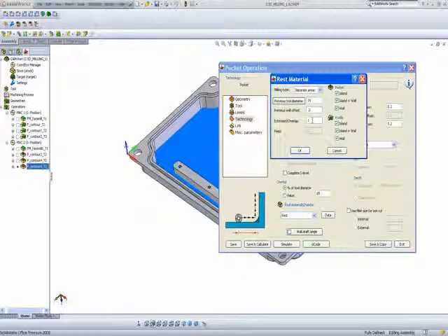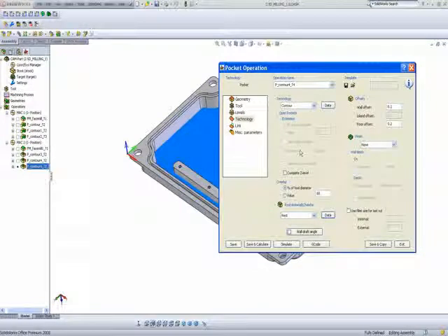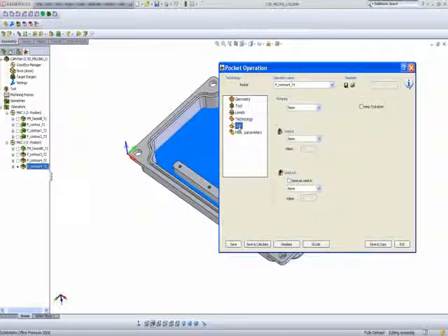What this does is very simple, is that right now I'll be cleaning in the area where the previous tool did not. But I would want it to start a specific distance away from where that area could not clean, so as to avoid having a mark on the part itself. I'll simply say OK. In my link area now, I will use a lead in, something I could not do before.